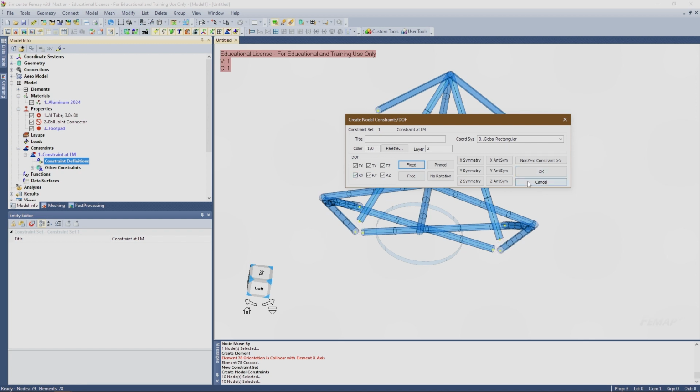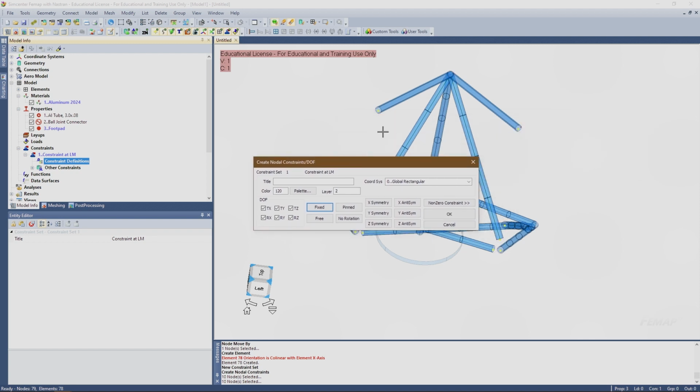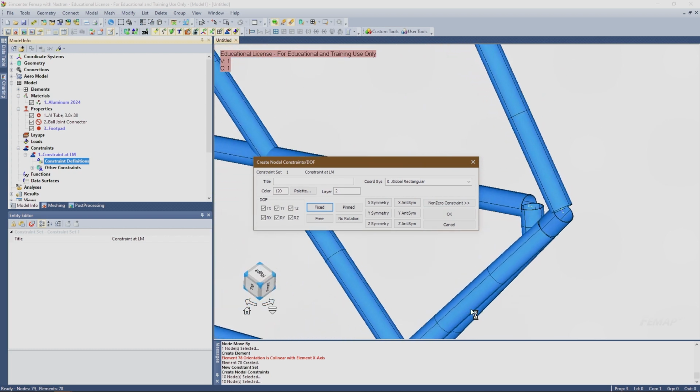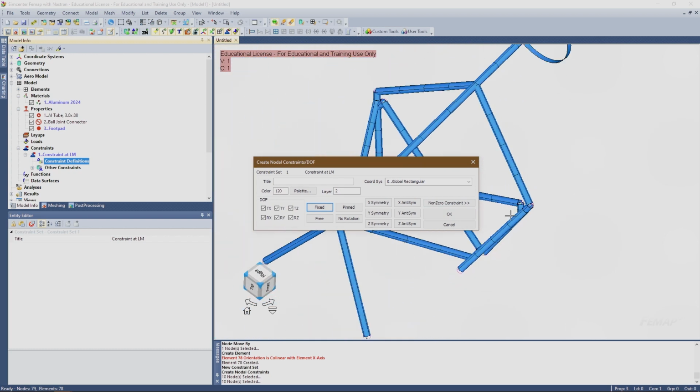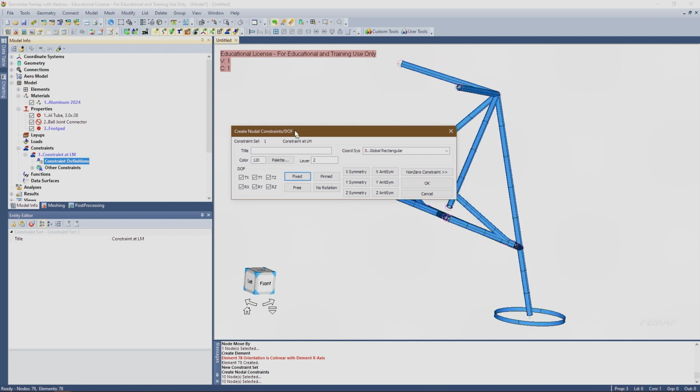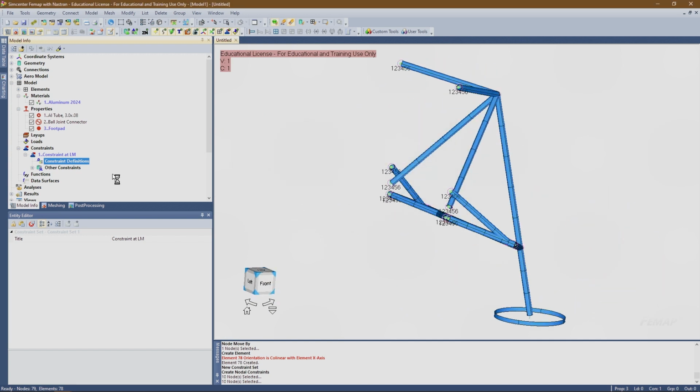But again, if we wanted to, we could constrain just the translations here and make that our ball joints. But again, we can't do that for all these intermittent joints like these guys, because if you constrain those to ground, this is essentially constraining them to ground, right?